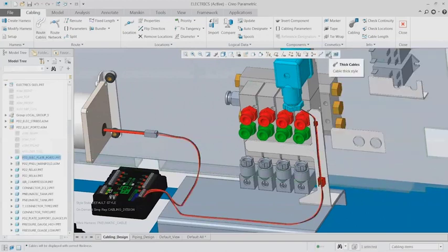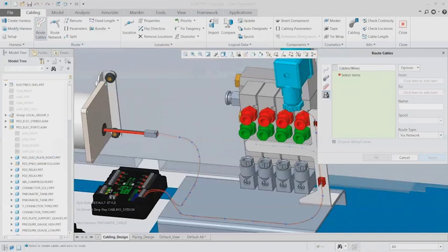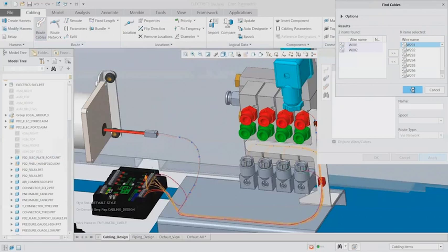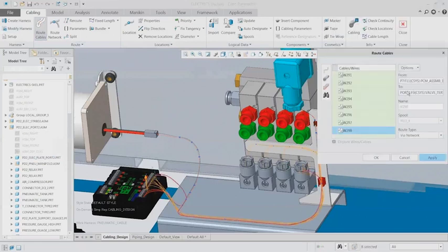So here we have that via a network, we routed 4 of those cables and they're already going into the correct location. We're going to continue doing some work. So we have a few more cables that we're going to route all at once. We have a large chunk here that are all going to a very similar location. We can move those all over. We're going to be routing those all at once. And then as soon as we move them over, you can see in the 3D model, it starts to give me a quick preview, as well as it fills out that information over there. And I can go through and individually choose each of those to see where they're going from, where they're going to, and how they're going to be routed.